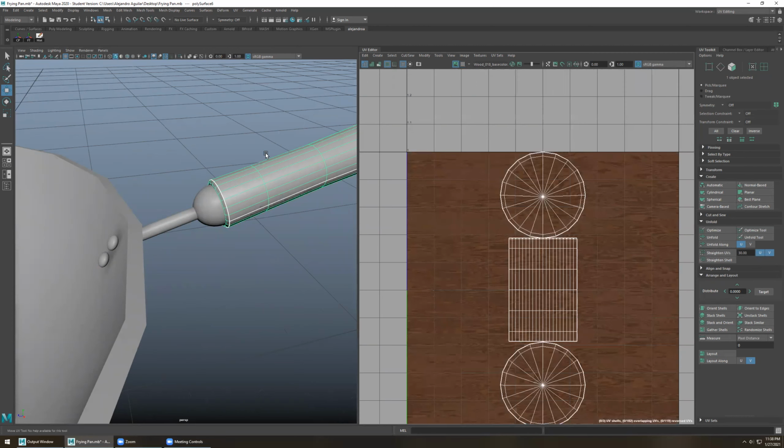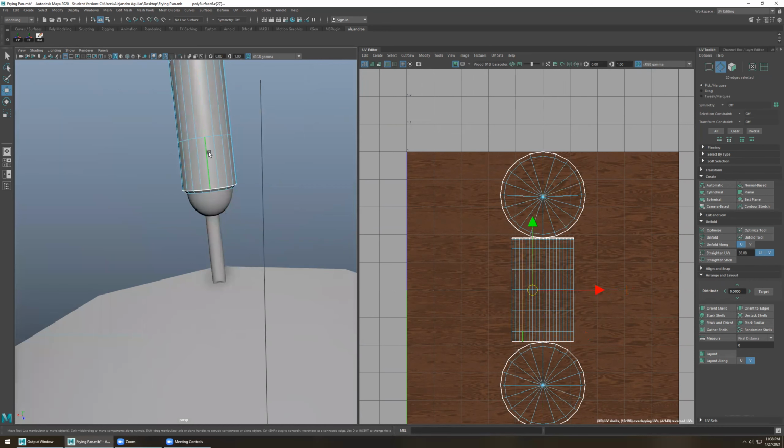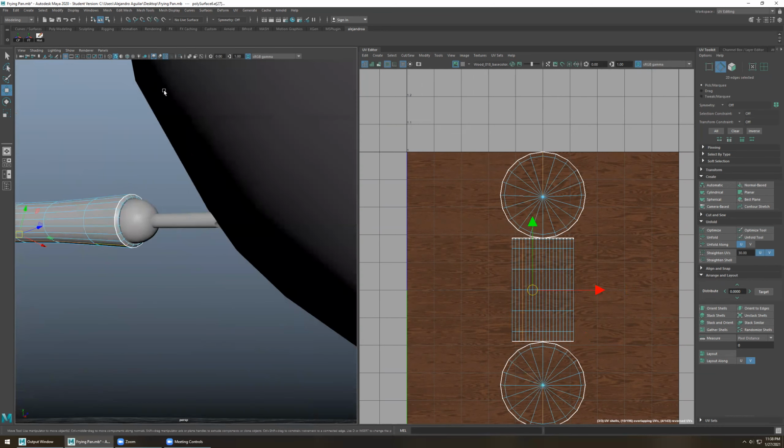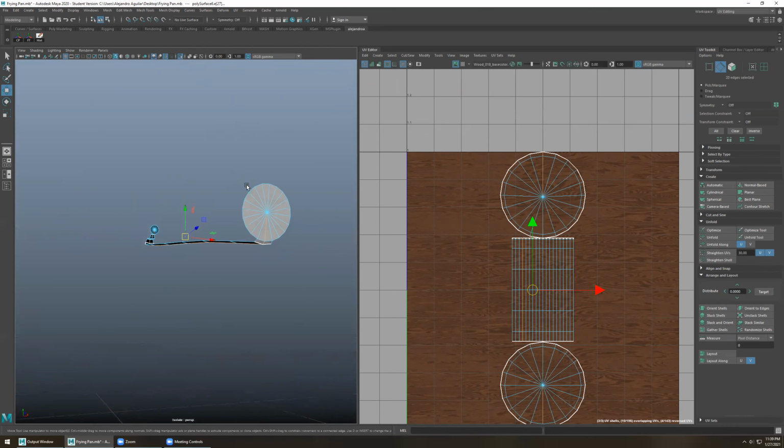And let me just turn off the checkered, see where we're at with this. Okay, so first things first, I'm just going to sew, then choose this edge, make sure. Oh, right. If you ever want to just work with what you have selected, you can press isolate select and it'll hide everything else. So keep in mind if you're working in a mode, it'll isolate even the object itself. So be careful with that. Be sure to select the object first and then isolate.